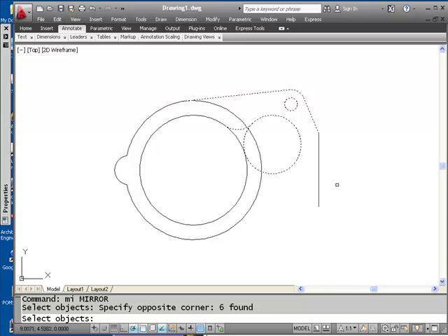That color that you're seeing, by the way, if it's not the traditional blue color, it's because of my software capturing, the video capturing device. So normally you're going to see a slightly different color, but it's going to work the same way, where my window is only going to pick things entirely inside it. So I didn't pick that line because it would give me 2 if I used the mirror command on it. And I didn't pick these circles for the same reason.